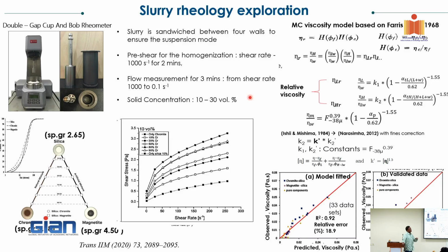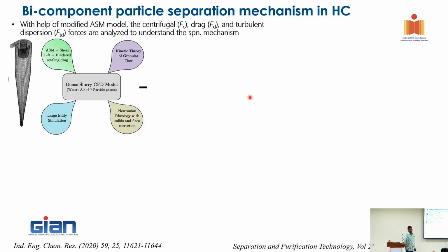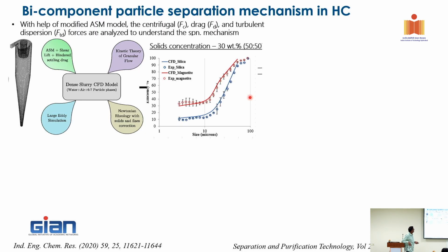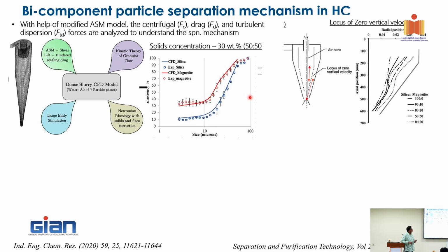And also if we utilize multi-component model performance predictions for cyclones, you can use viscosity as a parameter rather than a simple single parameter. So after that, we conducted the computational CFD model for the hydrocyclones to understand the cyclone separation in a much more detailed and insightful way. First, anything you try to do, you have to validate. We validated, and we could see the model predictions were pretty close, and we have also understood the separation mechanism by the classical equilibrium orbit theory.